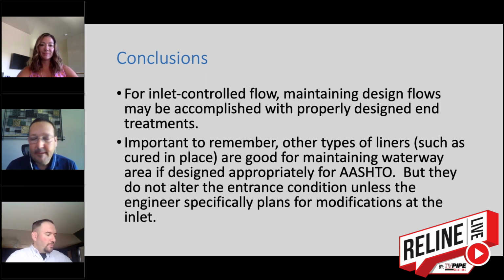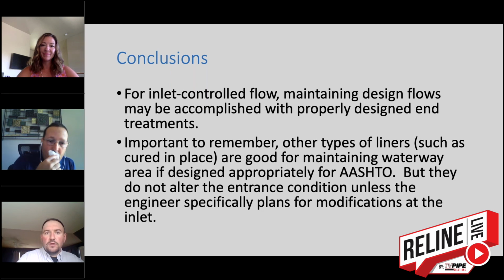Yeah, to the last bullet point, which Don kind of touched on, when other types of liners are utilized, typically there's no consideration for inlet modifications. So I would encourage folks, if they are considering a different type of inlet modification, or slip liner or liner solution, that they should look at the inlet, because again, it's heavily related to the entrance of the pipe and keeping headwater conditions down.